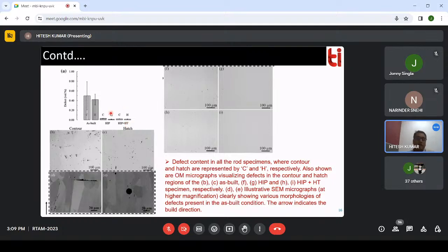So here, again, during cooling there are chances of more precipitates being present, because in nickel-based superalloys at about 900 degrees Celsius the presence of precipitates is going to change. So in the as-built condition there will be many defects. To overcome that, we heat the material and give it thermomechanical deformation, plus heat treatment, to remove the anisotropy of the material.